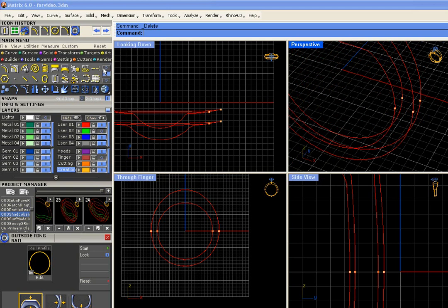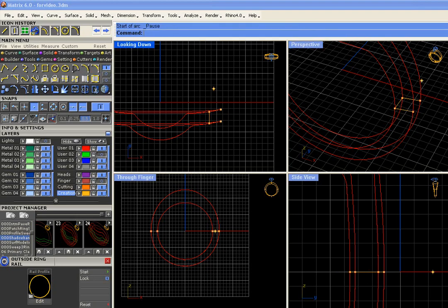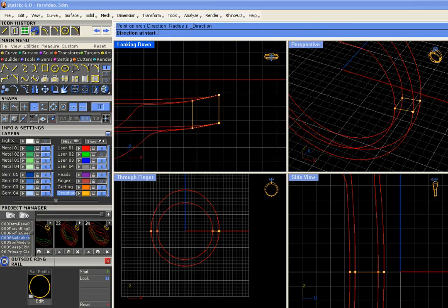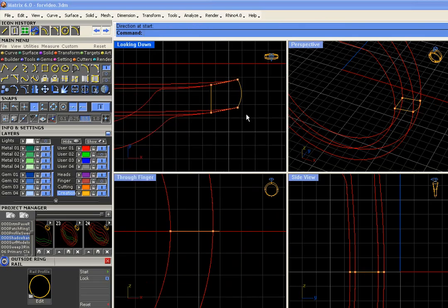So let's grab the creation layer, the line tool, and the point O snap, and just draw this point, point, point, point, point, point. Okay, for the last one we can draw an arc direction from each point and just pull it out with a little bit of curvature. Okay, we can join these all up, join. And if you wish to, you can fill out the edges so that your render comes out a little more smooth. Otherwise, you can leave it sharp.